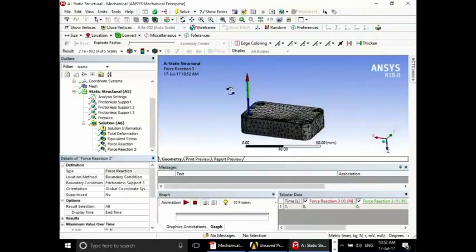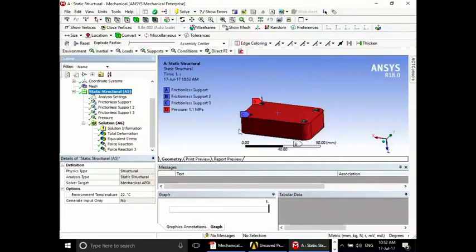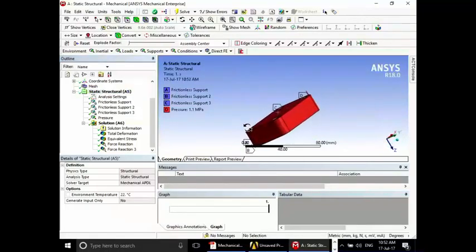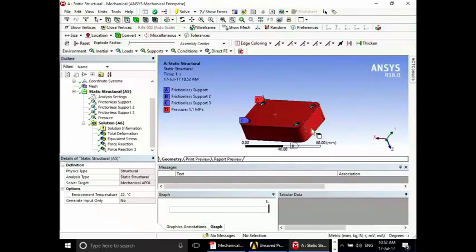To get an idea of what the total force in the Z direction is, X and Y will be balanced, because the pressure components in those directions are basically balanced, because there's equal area in those directions. But there's nothing to counterbalance the pressure in Z aside from the supports.